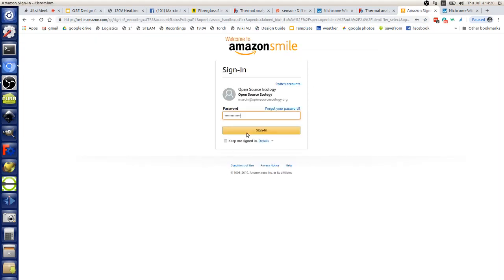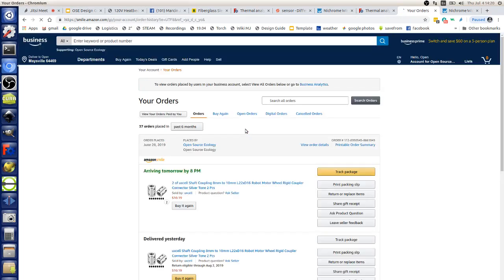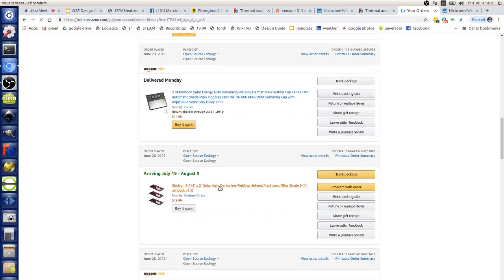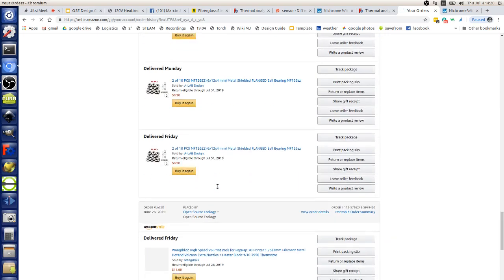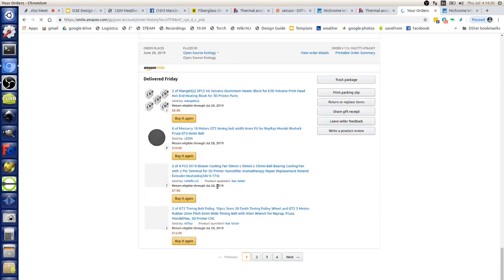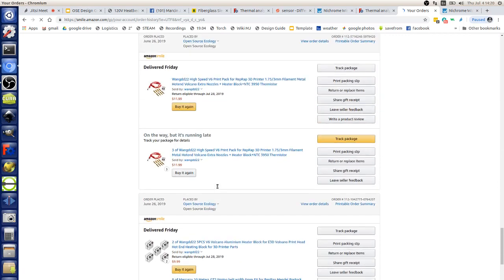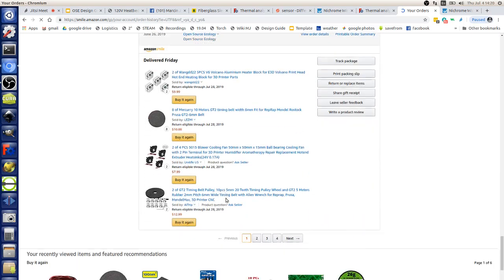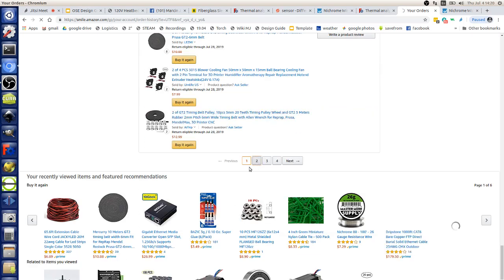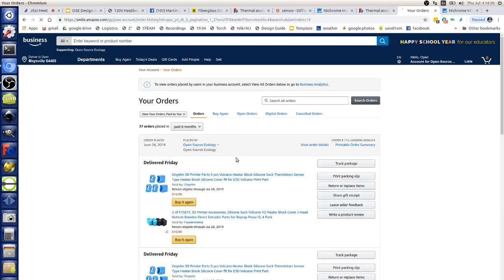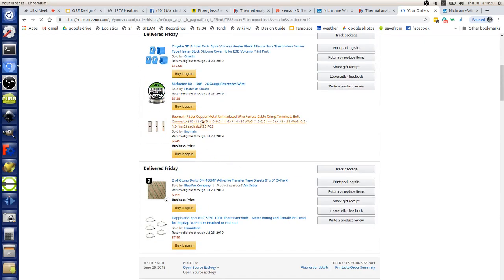Nichrome. For nichrome, you want to use sleeves that you use to crimp with. Simply because you cannot solder, you want to be very careful about what you're doing there.